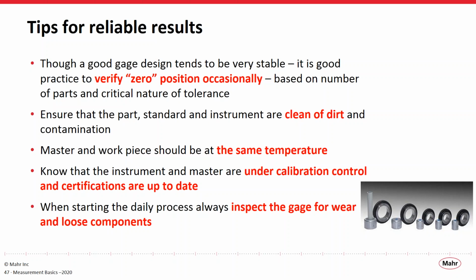With any gauging operation, we talk about gauges and measuring tools. It's good to bring a caliper back to its contact or back to zero every time to make sure that nothing has changed with the micrometer. Or it's good to put the gauge standard, the master ring or disc, onto the variable gauge and re-zero it, because you might get some offsets over time, temperature changes, dirt, and so forth. It's critical to re-zero occasionally and do that throughout the day.